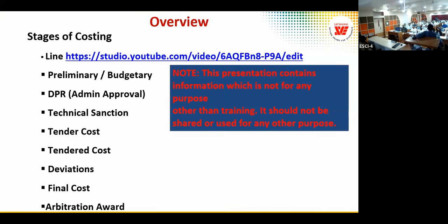Sir, in project works, SOR is generally not followed. It is item rate tender or SBT mode, where the DPR consultant or the agency submitting the tenders has the independence and opportunity to quote their own rates. In EPC mode projects, SOR is not followed. The contractor, the agency, the bidder has the right to quote their rate as per the prevailing market conditions. But for preparation of the DPR, it is only SOR which is the basis.